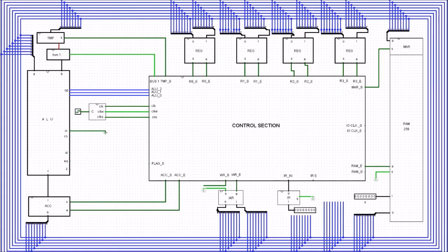So what you can see here is that we've disconnected the instruction register, so it means we can put in our own instruction. We wanted to put in this jump address instruction. So the jump address instruction is going to be the 1 here, and the rest of them are going to be zeros. Now what we want to do is jump to the contents of a memory location. So we'll make the contents of the memory location say 15.